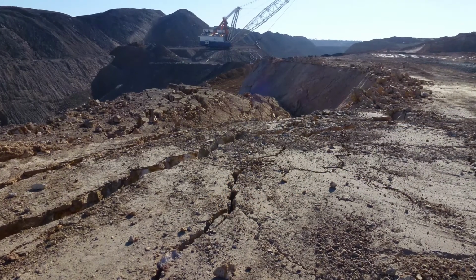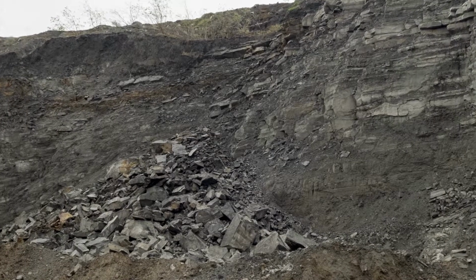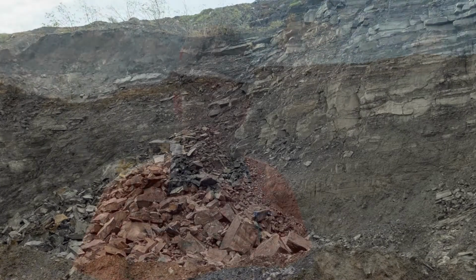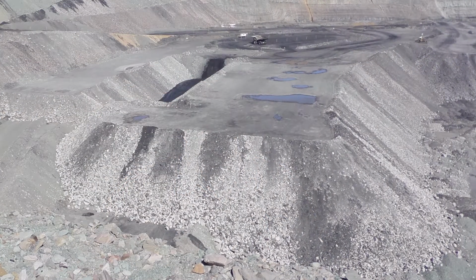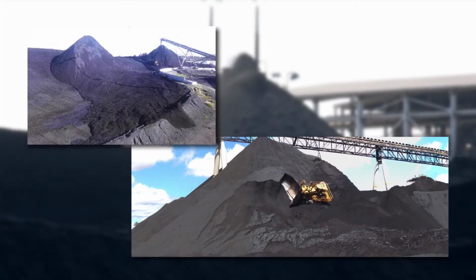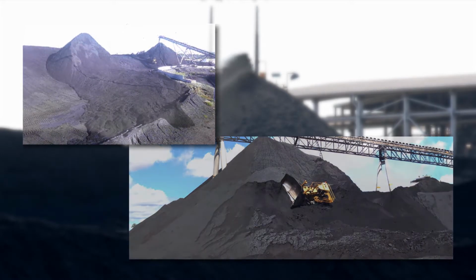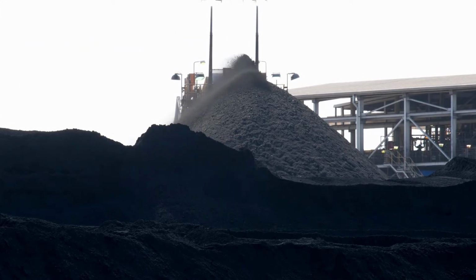As the factors that drive failure are different for excavated slopes and dumped slopes, the warning signs of these failures will be different. While there will be some overlap, there will be different warning signs for high wall, end wall and soft wall failures. There will also be similarities and differences between the warning signs for dumped slopes involving wet rejects, dragline spoil and truck and shovel waste. Slope failures also occur in coal stockpiles. You must be familiar with the warning signs for all types of excavated and dumped slopes.